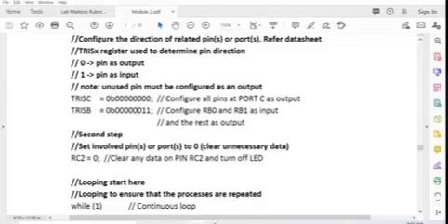So this means that you can use this code. If you are connecting port C to other types of devices, you need to configure individual pins. Right now we are not using any other pin other than RC2, so we can use this type of configuration.